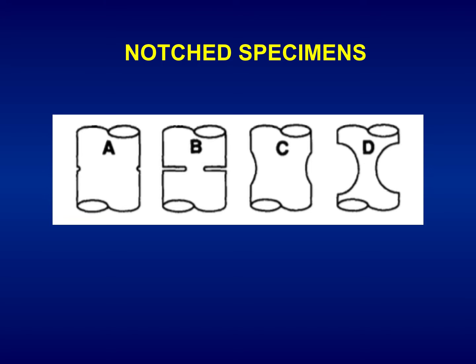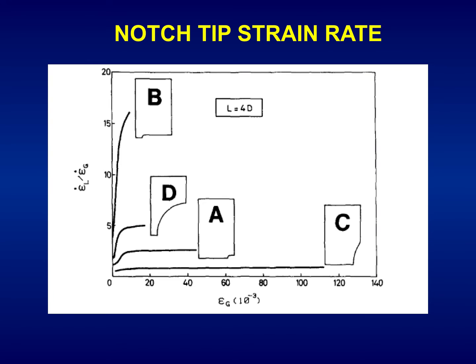Geometry C, maximum radius, minimum depth. In geometry D, maximum depth and radius. With these ABCD geometries, we cover the full range of stress triaxiality levels, thereby promoting different hydrostatic stress gradients governing the hydrogen entry in the sample, just to study the strain rate effects.